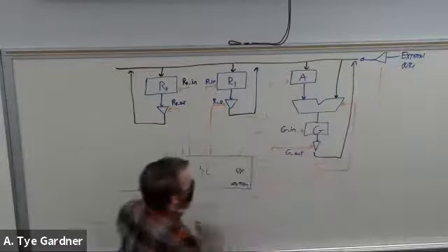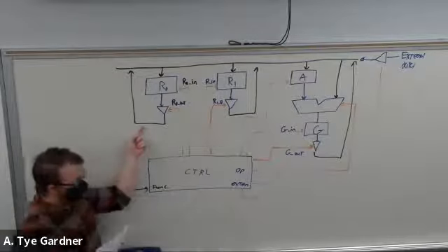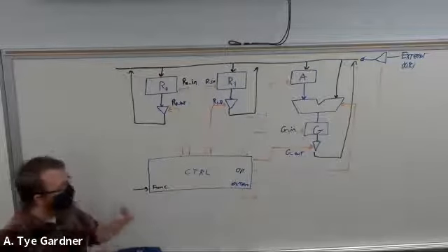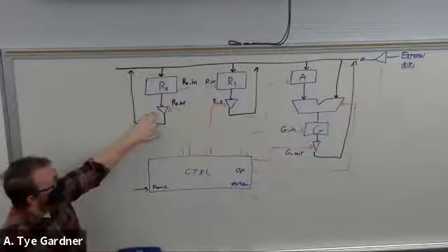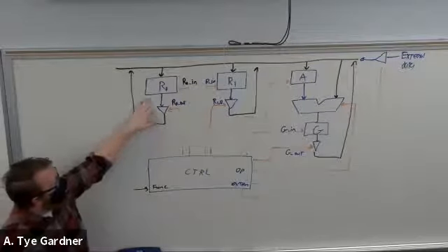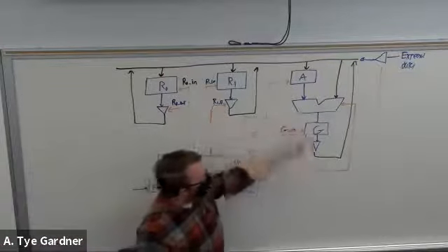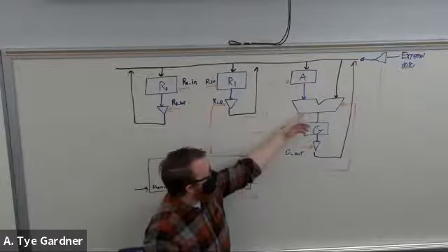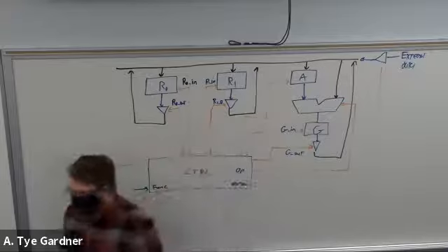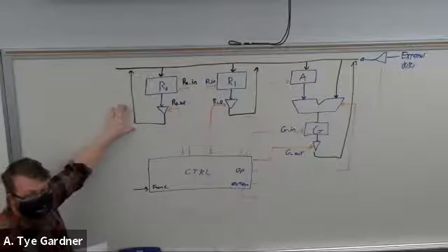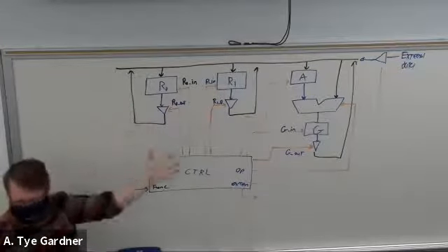Now you want logic such that you can never drive the bus from more than one source, because otherwise you're going to end up with conflicting data and potentially damage your parts. So where can that data come from? Well, it can come from this R0, the R1 out, the external data, or the G out, which is just a register to store the results of this opcode. Okay, so we want to add 3 plus 7. It asserts extern, and it pulls in the data, and now this bus has that external value on it because it's been enabled.